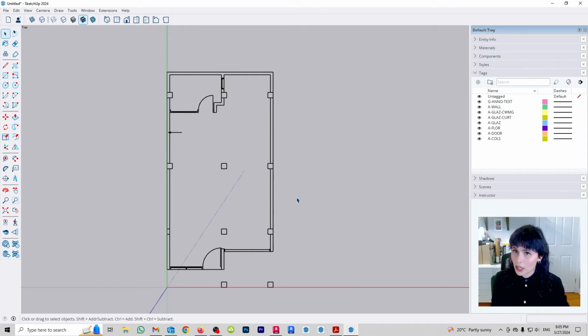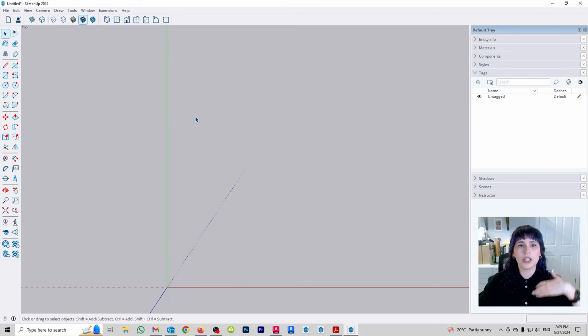So depending on what you're importing, sometimes you're going to bring in a file and you're going to notice that no matter what you do, the model units don't seem to work. SketchUp just doesn't understand what it is supposed to do. So what do we do in those cases? Well, in those cases, you can manually override the unit system that your CAD references will be imported in.